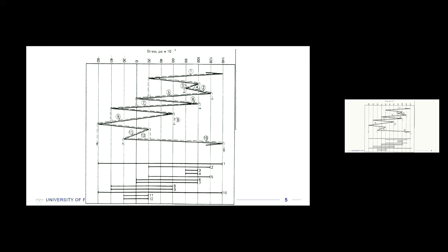And so here's the kind of rain flow diagram. What I really like about this is that they've drawn the magnitudes down below. So for example, if I just show like segment number 1 here, which goes all the way like that, then it shows segment 1 here across all of them, right? So then you can go up and look at the different segments and see that they're all sort of paired up, and that they can represent the spectrum of loading in some fully reversed cycles. So I'm just going to move past that, and then we're going to make some tables on these different segments here and how many. We don't know exactly what order they fall in, but in a single block, it doesn't really matter. We're going to calculate the damage for one whole block because they go in order, and then we'll do another block, another block, another block.